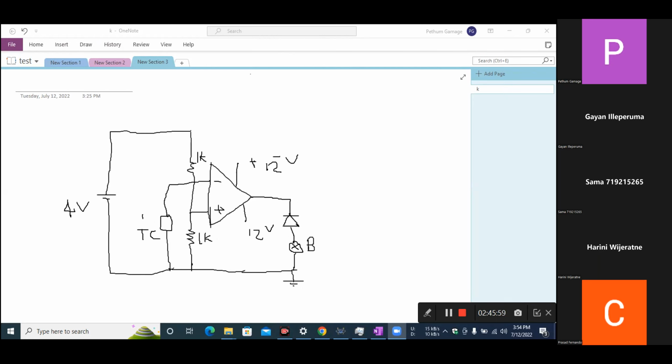Zener diode can connect parallel to buzzer. No, not the buzzer, right? You want to have a fixed voltage for what purpose? We were talking about the comparison with a reference voltage, so the buzzer side is not relevant. The buzzer side is the output. The input sensing and the comparison part is where we need a better comparison. That is, the middle part, the processing unit.